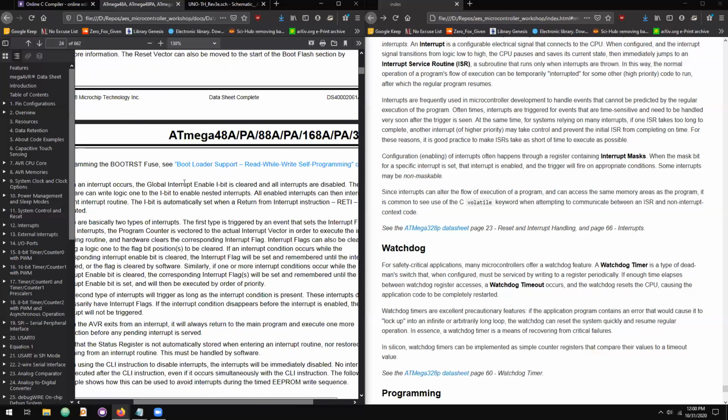So you have to have both this global interrupt enable bit and the dedicated mask for your interrupt. Both of those have to be set for the interrupt to occur. It's possible to run your microcontroller without interrupts at all, in which case you would probably just clear this bit. And you can totally execute like that. But for the majority of applications, we will be using interrupts because there's typically some time critical part of an application.